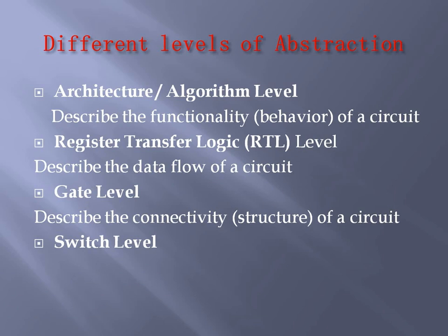So when we model with this hardware description language, that is, when we write the code, you can write in behavioral modeling, that is complete behavior, or just as a flow of input data to output, that is RTL, or gate level, that is interconnection of components. That level also we can write the code in. And lastly, the base level is the switch level using MOSFETs.